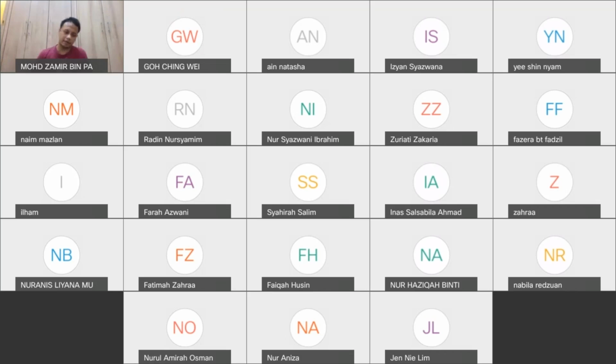Okay, PSM. I didn't mention it; I just flew through PSM. PSM is one strategy you can use to resolve the small features printing problem, because if you print too small, then at some point the features cannot be resolved by your exposure process or by your mask, because they may be too close together and the signal is continuous and the scanning system cannot distinguish that.